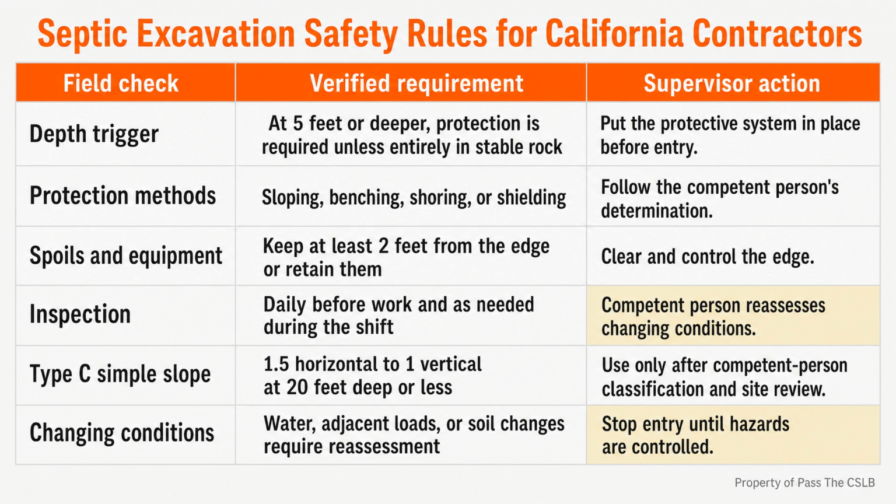The General B supervision move is simple and firm. Do not let production pressure turn a tank excavation into an unprotected entry. Stop the work, clear the edge, get the competent person's decision, and install the required protection.